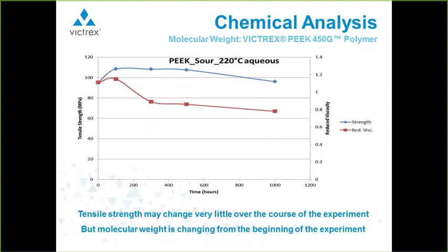And one of the things we do at Victrex is we look at residual viscosity of the polymer, which is a great indication of molecular weight, to tell us what changes are actually occurring on a molecular basis.